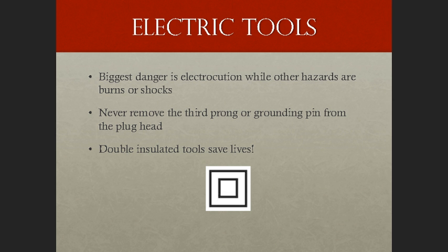Electric tools. Employees using electric tools must be aware of several dangers. The most serious is the possibility of electrocution. Among the chief hazards of electrically powered tools are burns and slight shocks, which can lead to injuries or even heart failure. Under certain conditions, even a small amount of current can result in fibrillation of the heart and eventual death. A shock also can cause the user to fall off of a ladder or other elevated work surface.